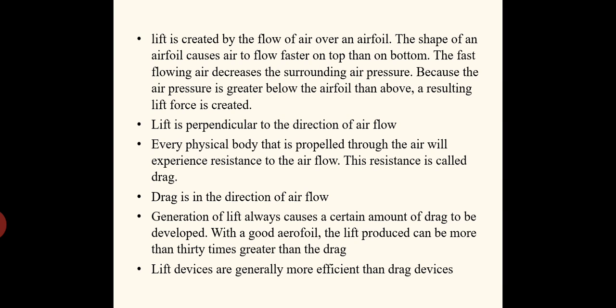Now coming to the drag, every physical body that is propelled through the air will experience a resistance to airflow. This resistance is called the drag. Drag is always in the direction of the airflow. So two forces are there in a flow field. One is drag force, which always acts along the direction of the flow, and lift is always perpendicular to the direction of the flow.